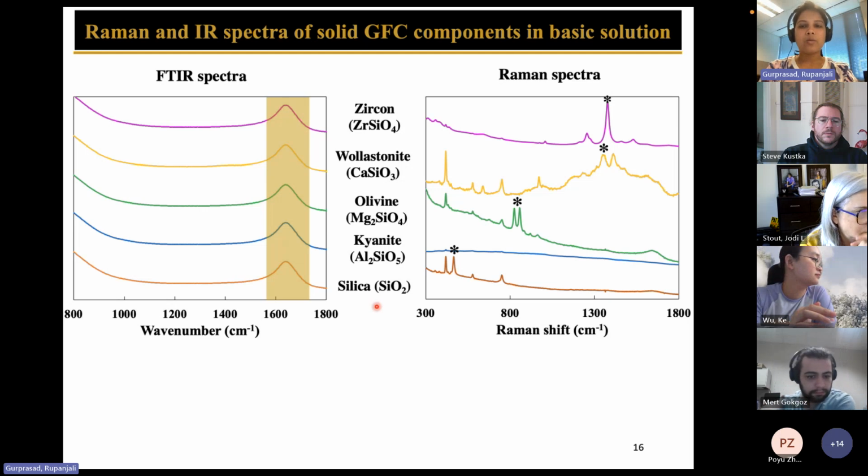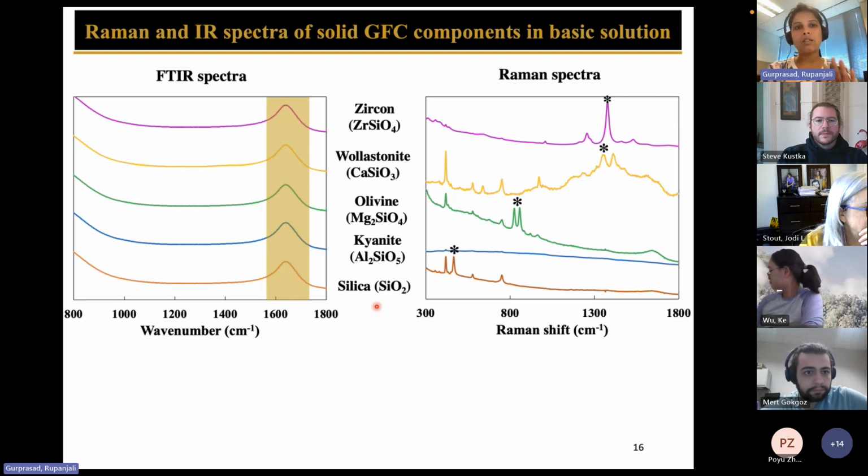One thing at this point that I would mention is that in the case of silica and silicates, we started observing a slight fouling of our IR probes. Fouling is essentially a solid deposition of the components on the probe itself. So before taking a reference for the silica or the other silicates, we always cleaned the probe before taking a neat and clean spectrum.